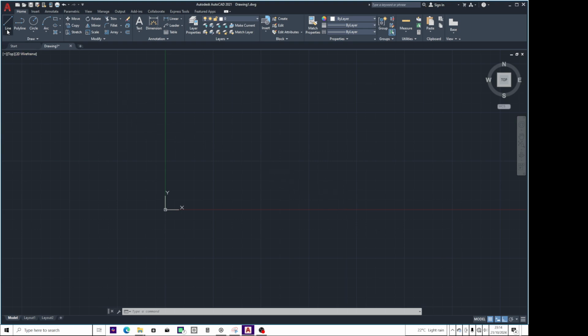When I activate auto mode, you can only draw across the quadrant angles. Once I have my line and I click, then give direction, even if I'm off, you see that it snaps over 0 or snaps over 90, 180 and 270 and back to 0 or 360.